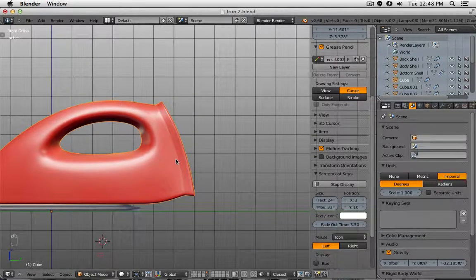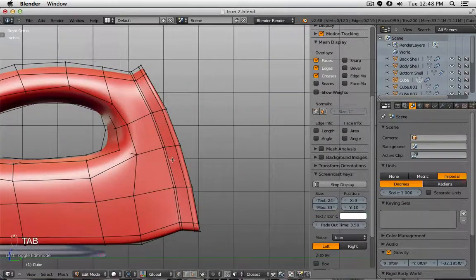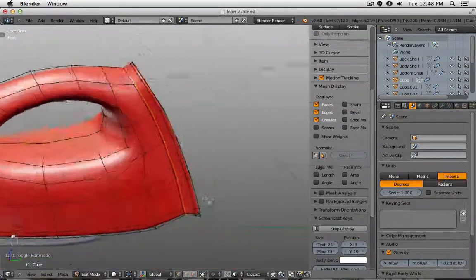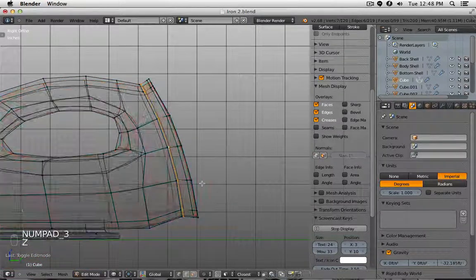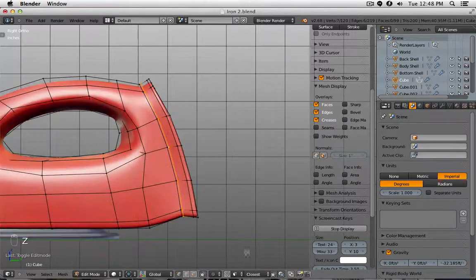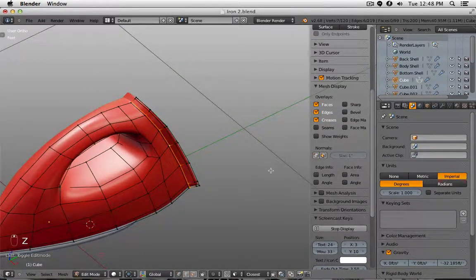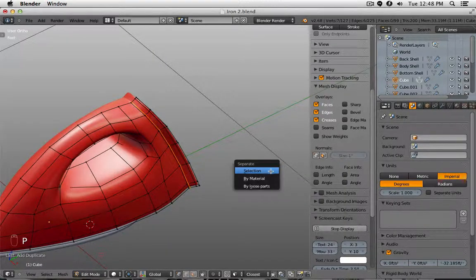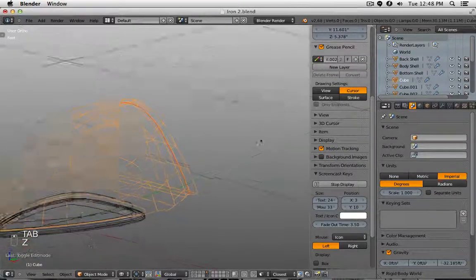Because you see that this one, while to a certain degree being flexible, was also more labor intensive, and there's a different approach we could use. So I'm going to try to select only points that, for example, express a cross-section view like this. So these points I select, press Shift D to duplicate, press Escape, press P to separate, and then leave edit mode.